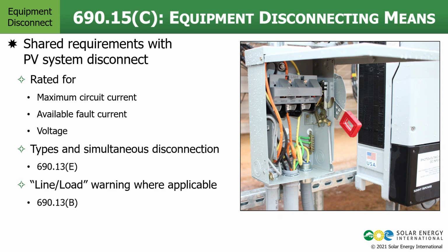We need to install that line load warning when it is necessary. That's the warning we discussed earlier that says electrical shock hazard, terminals on the line and load side may be energized in the open position. And keep in mind, as we mentioned earlier, that this is only applicable to places where the line and load terminals actually may be energized when the disconnect is open.